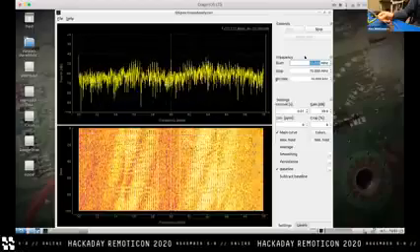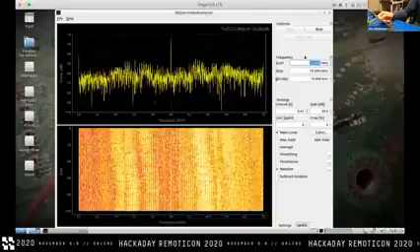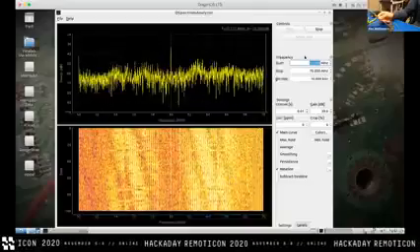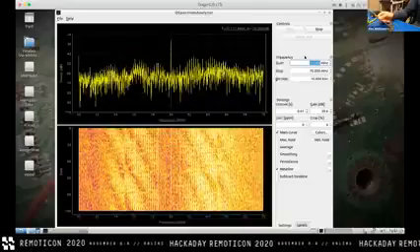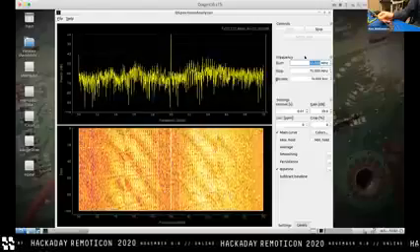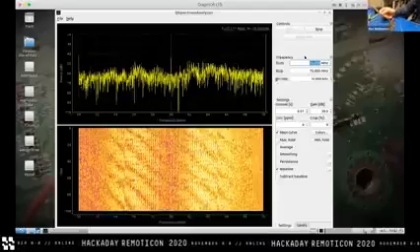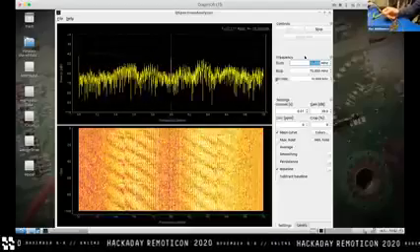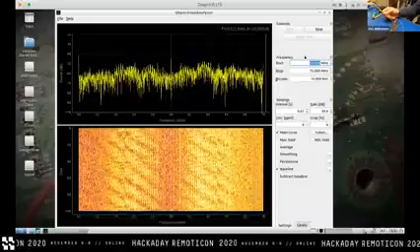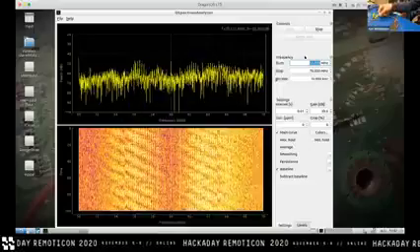Now we can definitely see that 60 megahertz peak driving up and down as I move around near the offending pin. It looks a whole lot like I'm off the charts there. Yep, and I stopped directly on top of that decoupling capacitor that I believe is just right next to the 60 megahertz output. Yeah, so that's a pretty successful test in my book.